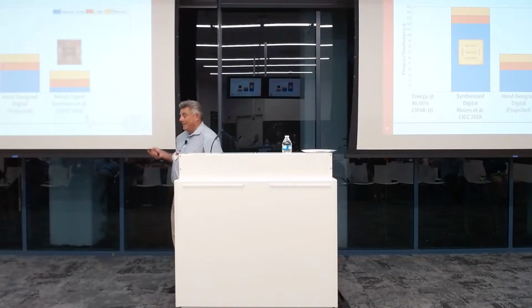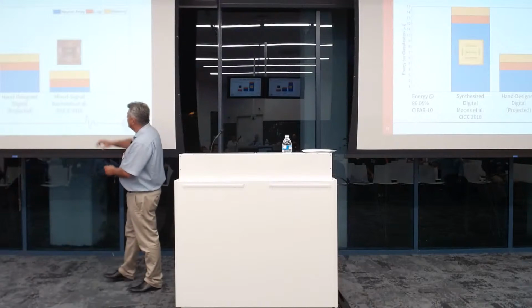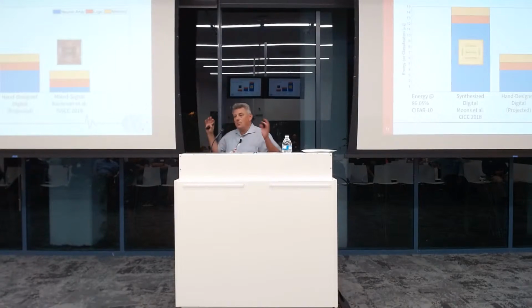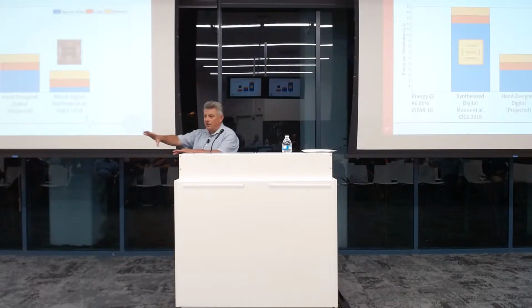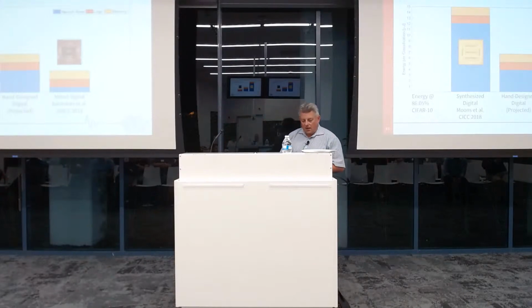Then this thing is actually within a factor of 2 between digital and analog. And so one of the take-homes is, even if I cut my neuron energy to 0, this blue thing, I still have all this baseline because of logic and memory that is there no matter what. So even if you give me an analog fabric that has 1,000,000 tops per watt, and then I put this logic and memory around it to talk to it, it's over. Then I'm just as good as the digital guys. And this is something to keep in mind. You actually have to make sure that whatever you put around these things doesn't drag them down.